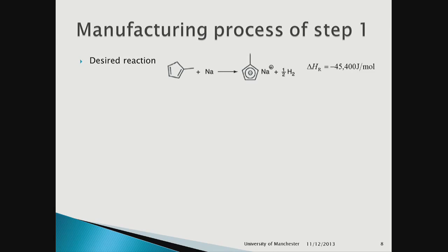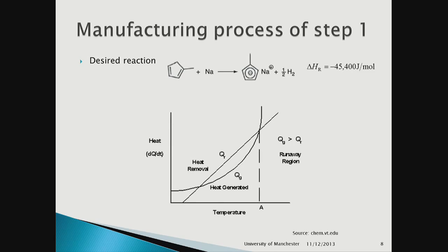So anything that's 100 kilojoules per mole is going to be massively exothermic or massively endothermic. 50 is quite large, 10 is not large. So if I've got an exotherm of minus 10 kilojoules per mole, I'm going to go, oh, it'll warm up a few degrees, it's not too bad, depending on the total volume of what we've got. If I've got one of 50, I'm going to be a bit worried. If I've got one of 100, I'm very worried before I start. But if you just think about that, you'll remember that for design. Those are numbers that are important.